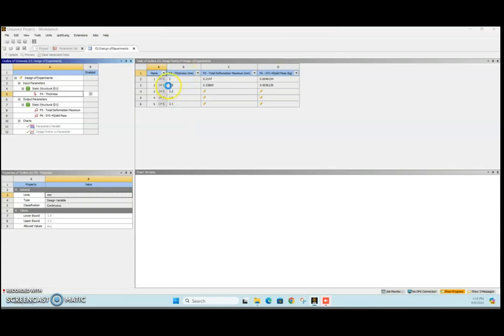Okay, so you can see that it has completed earlier the current thickness, which is 2. Then it starts with 1.8. You find that this is the deformation. It doesn't exceed 0.3 mm either. Then the mass is reduced. So we will look into other design points. Of course, this is quite straightforward. So you can immediately see which design point can fulfill your design constraint or the criteria, right?